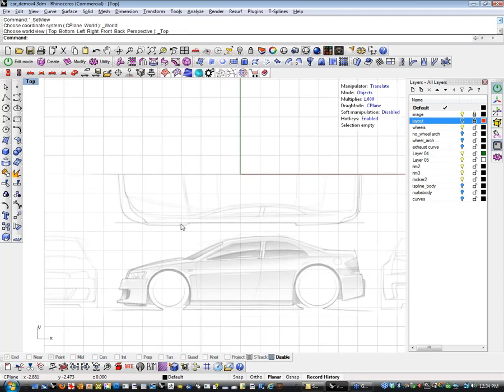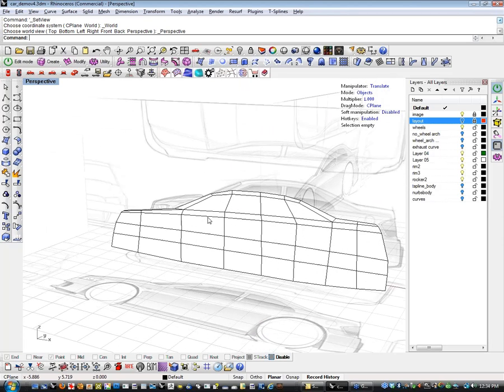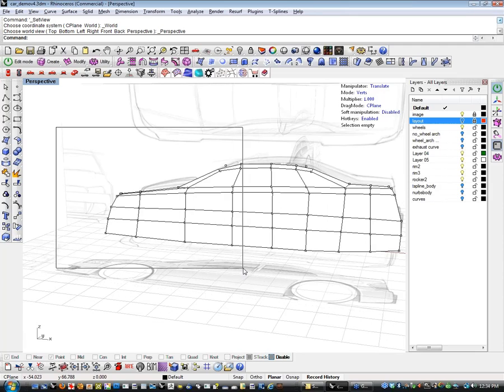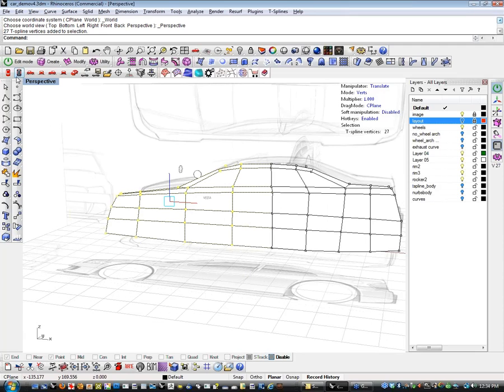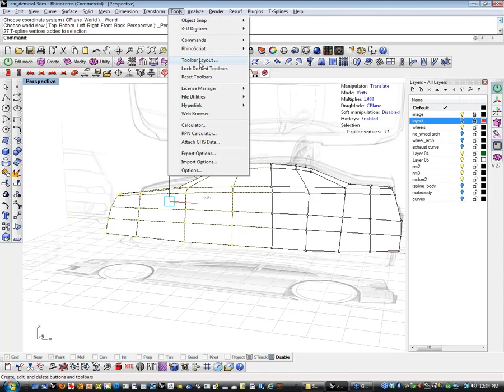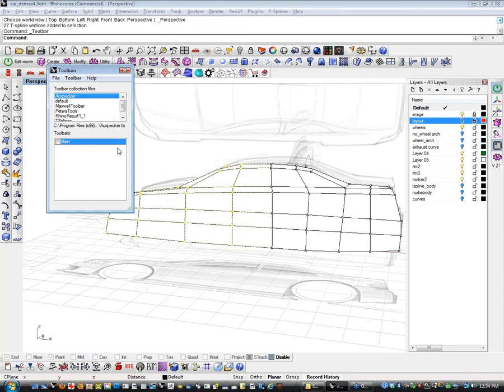And cars are not dead straight. They're never made like cut pieces of 2x4. They've always got a little bit of taper in the front, always got a little taper in the rear. And one of my favorite tricks is to use the UDT tools, the Universal Deformation tools within Rhino. If you don't have them or if you haven't used them, punch yourself in the face because they are the most awesome tools in the Rhino toolbox.